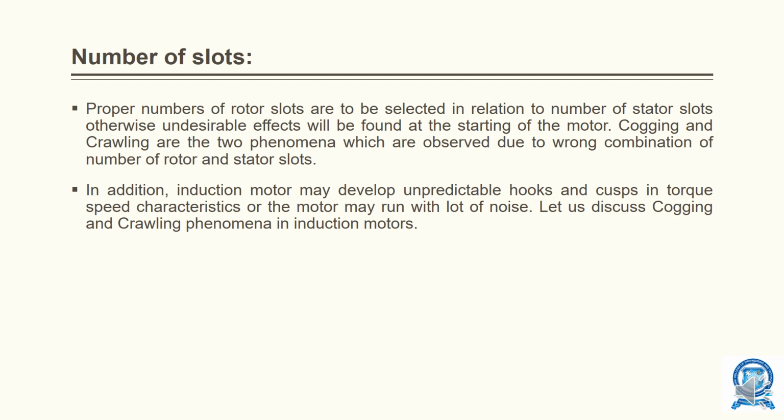So we know that capital D is the main dimension. We know how to calculate the main dimension, the stator diameter. Now with the help of this, the rotor diameter Dr is equal to main dimension D of stator minus 2 times Lg. Lg represents the length of air gap. So this is all about the diameter of rotor.